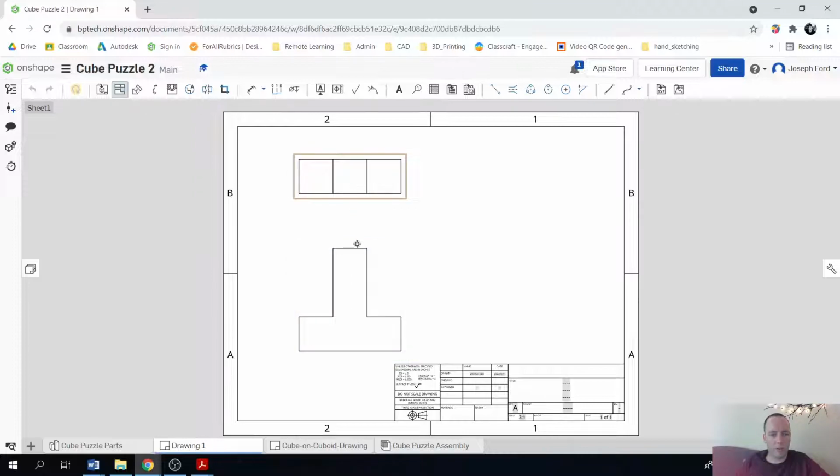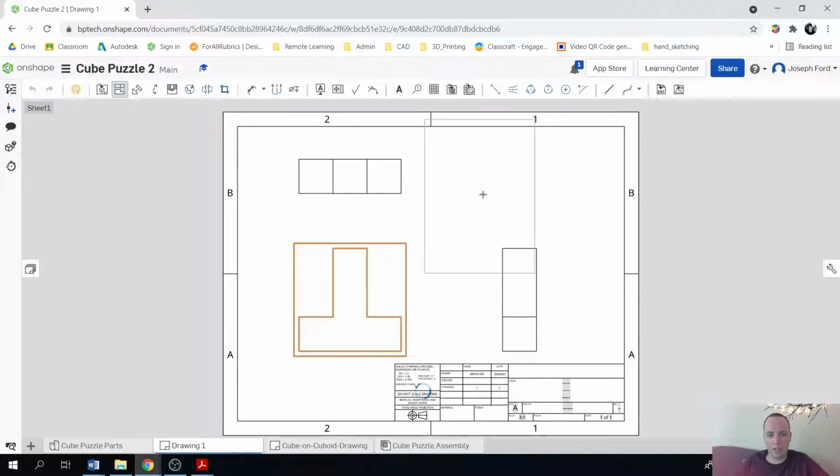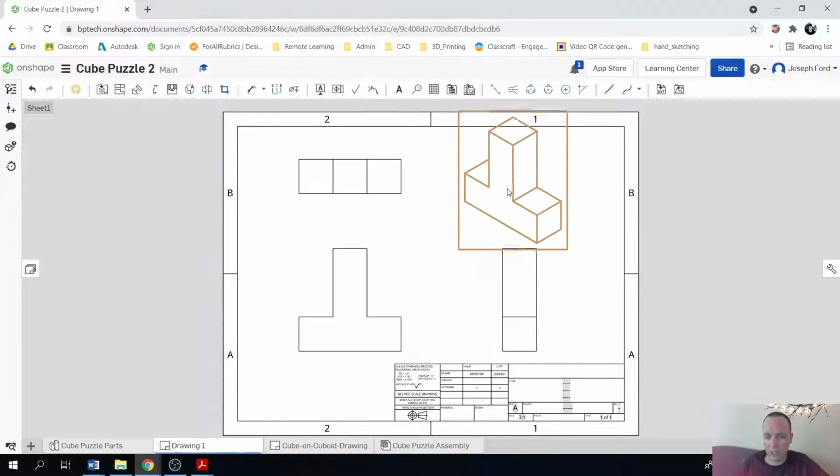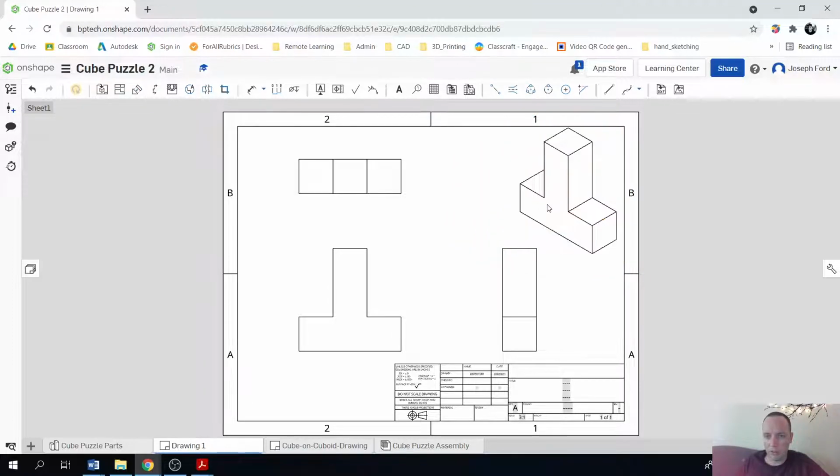So I just dragged up the top, and again, I'm on that project tool. So I'm going to click again, and it's projecting the view. I'm going to project that view. Oop. And don't panic. If you remember, that tool is still on. If you click on something else, it's just going to keep projecting. So you need to hit escape to get out of that projecting tool. And now you can go ahead and move things around.